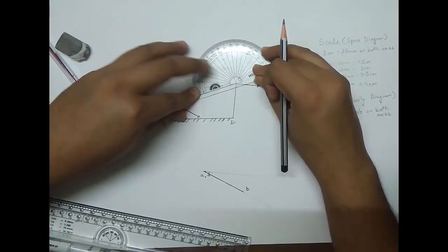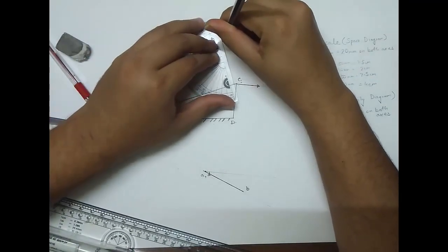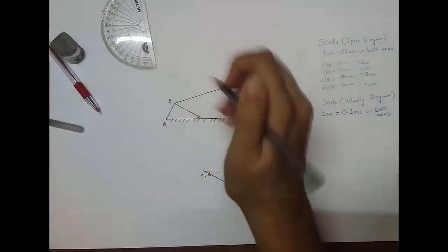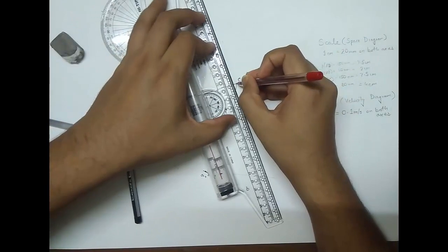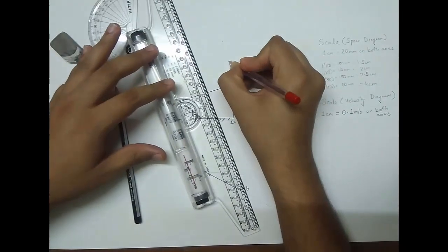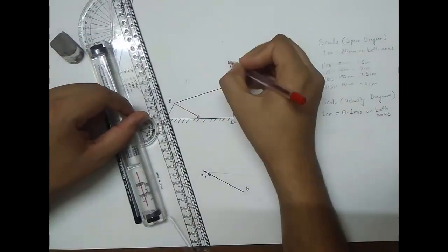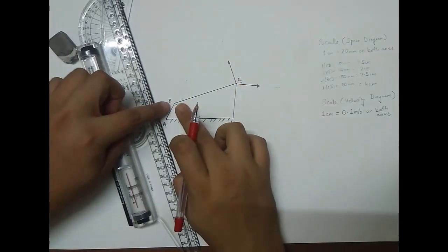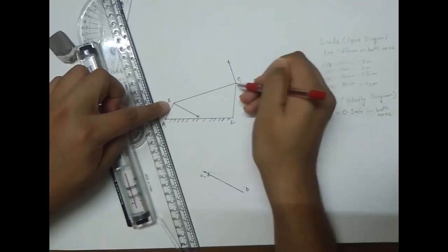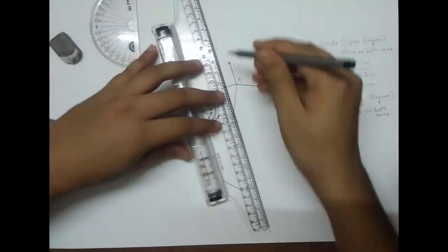Velocity of C with respect to B will be perpendicular to BC. Okay. So drawing this. Now this will be the direction of velocity of C with respect to B. This is direction of velocity of C with respect to D. This is direction of velocity of C with respect to B. Okay, this is C with respect to B, C with respect to D. Okay, so again